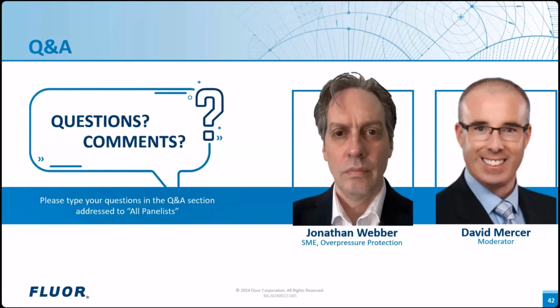All right, very good. The next question that's come in here: are there cases when a HIPPS system is used for scenarios other than to replace a PSV? Yes, well, we see them also used to reduce the required relief load on the PSV.